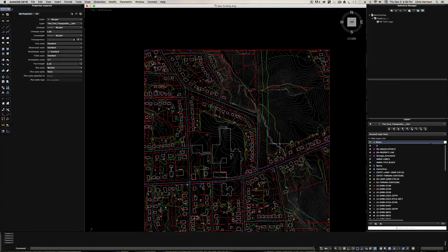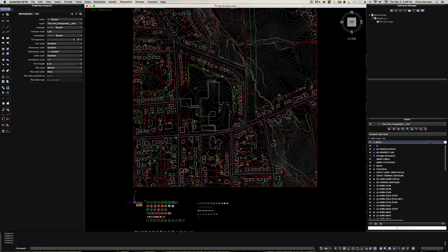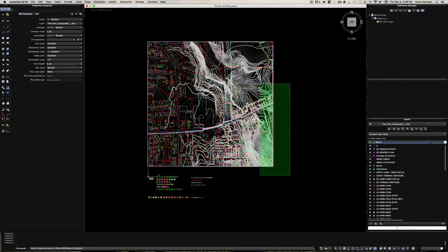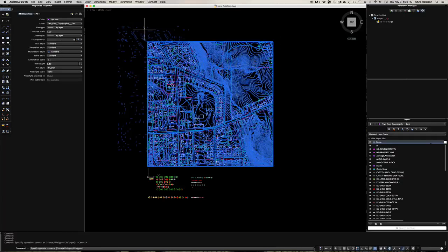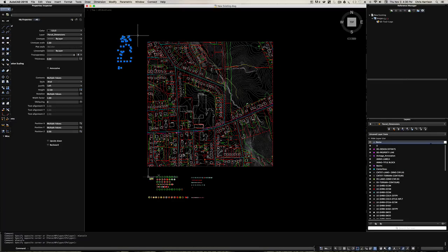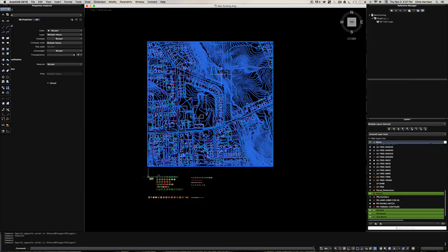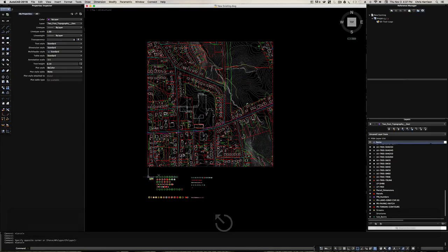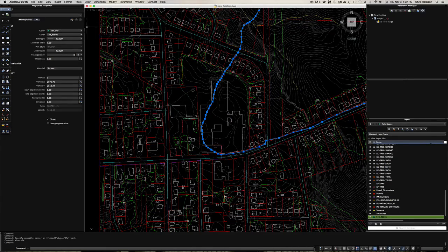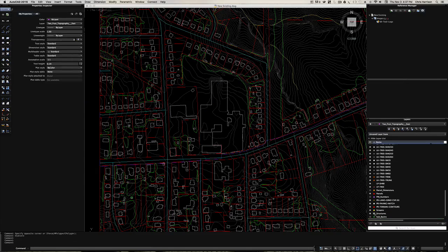Okay. All right. So we're gonna create a W block from this thing. I'm gonna select all the information. And ooh, what's that? Parcel dimensions. Okay, let's go ahead and make sure we turn all that stuff off. Parcel dimensions, don't want that. Pin number should be off. Anything else weird? Okay. Everything else looks cool. Oh, I said I don't want the basins either, so let me get rid of those. You could model those, but I'm just gonna simplify this, so I'm not gonna do that.